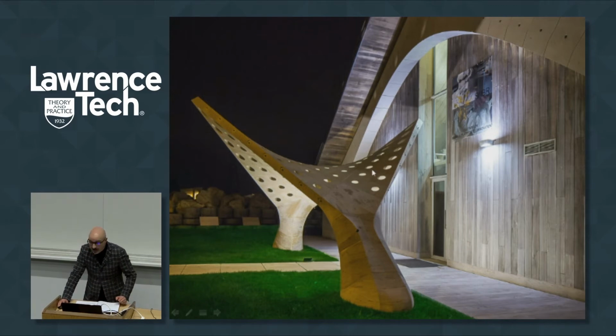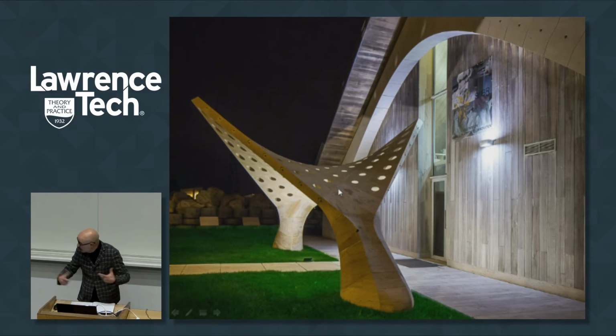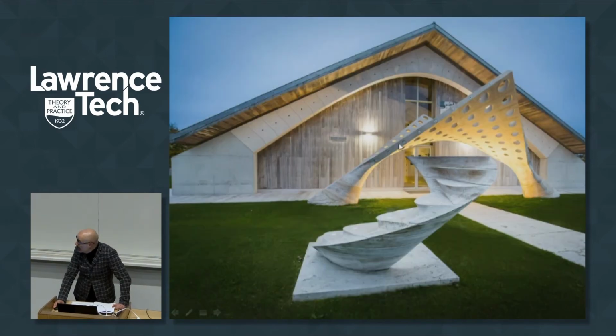And so because the stones are not glued together, because of the vault condition, you can find a straight line inside the joint of the ashlar. And so you can put inside a pre-stressed bar, a cable, and thanks to this condition, the structure works very, very well.